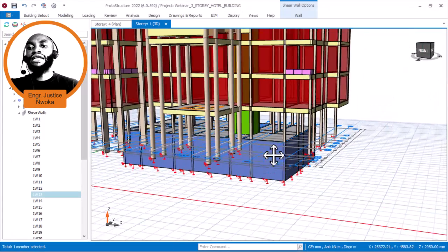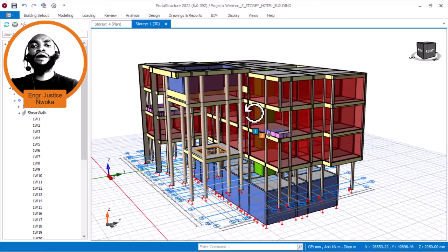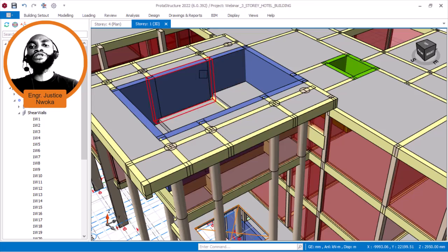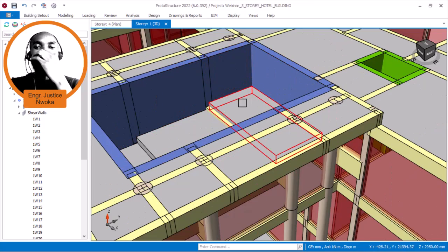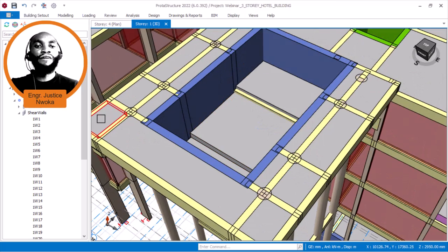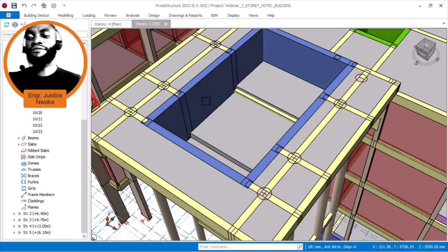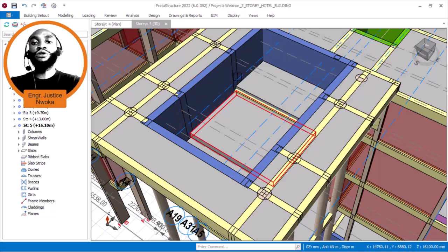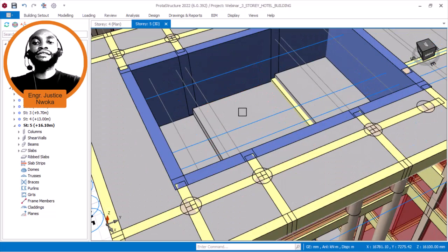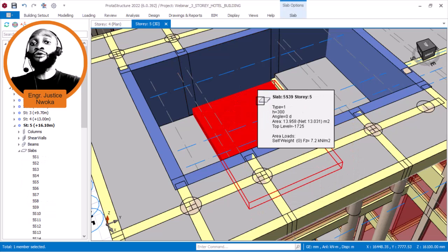Okay, so with this we have now applied load on all our basement walls. Let's now also apply load on our swimming pool wall and our swimming pool slab, because there is no load here. So let us navigate to Story 5, which is the last floor where the pool is. Now once it's active, let's look at this slab here, for this basement, for this swimming pool.